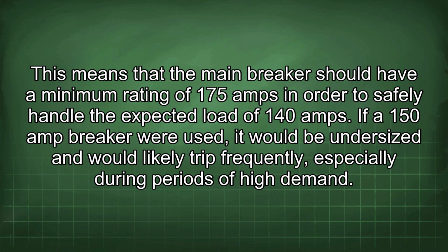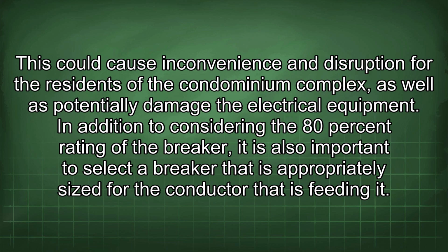If a 150 amp breaker were used, it would be undersized and would likely trip frequently, especially during periods of high demand. This could cause inconvenience and disruption for the residents of the condominium complex, as well as potentially damage the electrical equipment. In addition to considering the 80% rating of the breaker, it is also important to select a